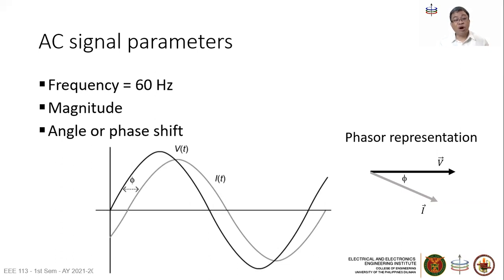The magnitude of the sinusoidal signal is likewise important. In high school math, we use the amplitude, the peak value, to characterize the sinusoid. In this course, we will eventually use the effective value of the sinusoid as the magnitude. If you use a multimeter, just as we showed earlier, it will measure and show you the effective value. And we'll describe it a little bit more later.